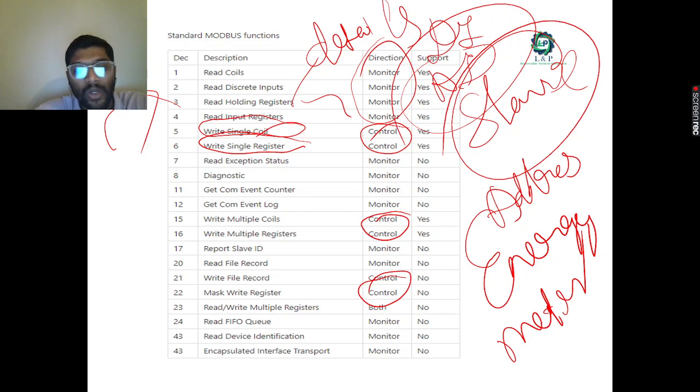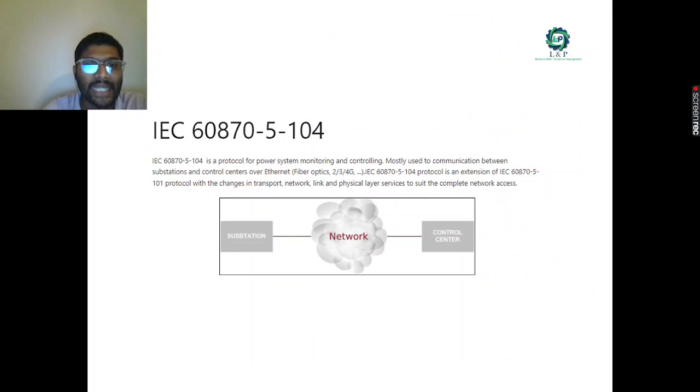Most importantly, if you're going to read any sort of values, go with the monitoring option. Whether you're going to write anything or command anything, better to go with the control operations. So you need to be precise and very clear about those things when creating the tags.